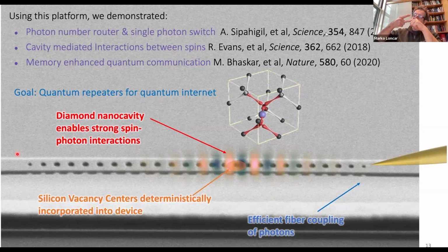And then you have now these evanescent fields of optical fiber and diamond waveguide. They kind of couple and make a directional coupler that is tapered. So that allows light from the fiber to, with extremely high efficiency, hop onto diamond, hit the cavity, bounce back and go back to the fiber with, as I said, 99% or so. 0.15 dB is, I think, at the moment, coupling efficiency per pass. And then that allows you to essentially make various gates by coupling silicon vacancy strongly to optical cavity and coupling cavity to the fiber. So maybe I'll just stop here, CJ, and you can take over.